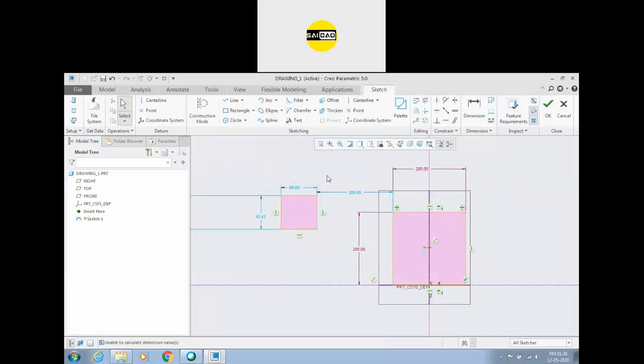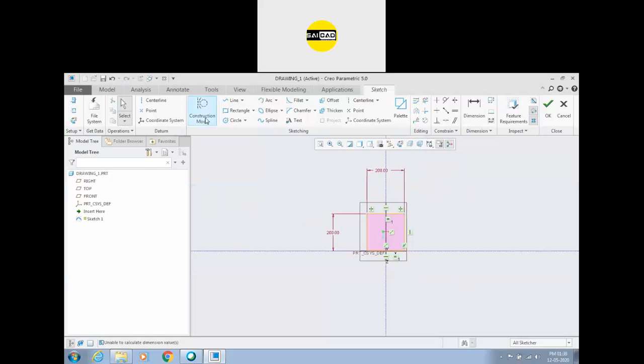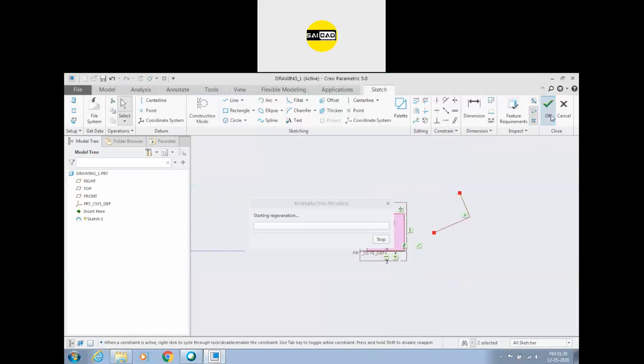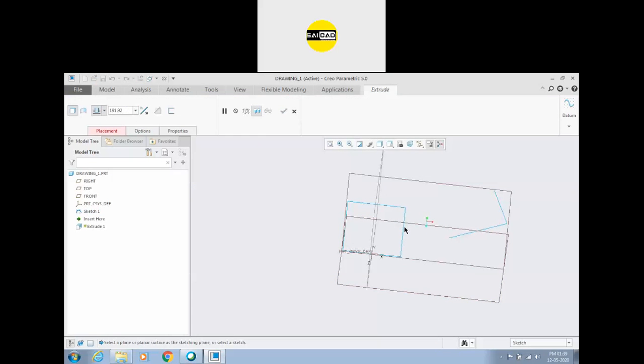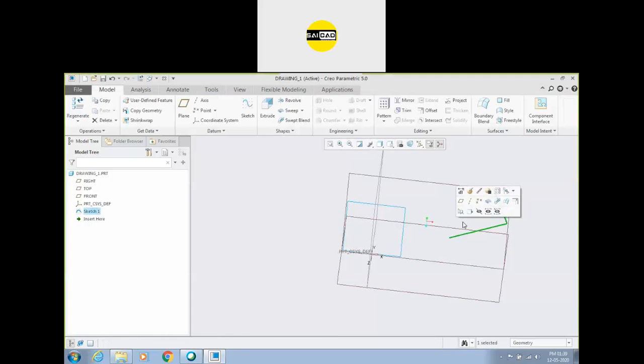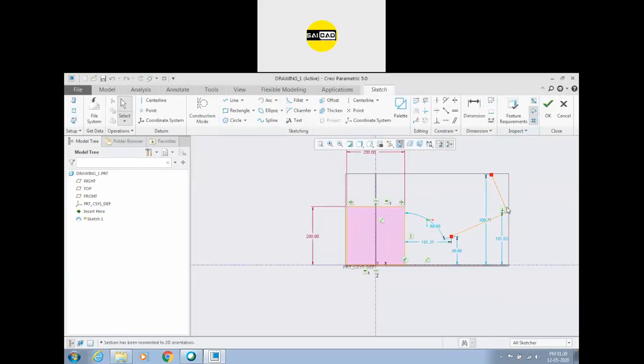Okay, so Creo Parametric does not support the open entity sketch. If we select a single object, some line, and we close, we will not be able to convert it into 3D. So we have to use these options to determine if our sketch is closed or open.